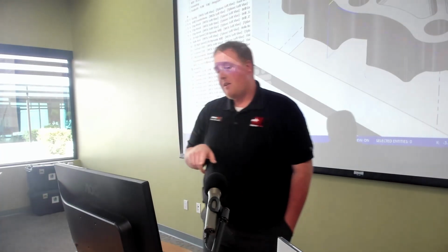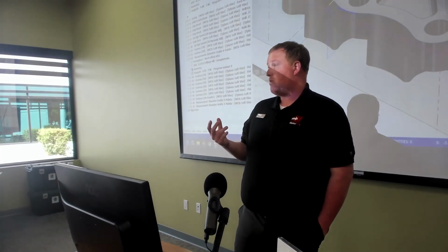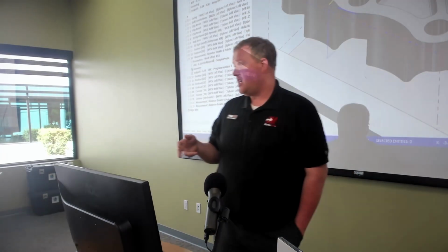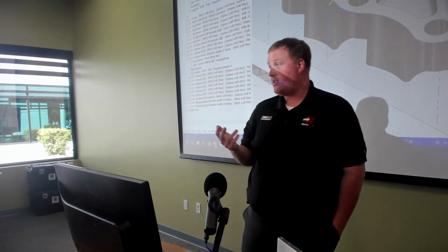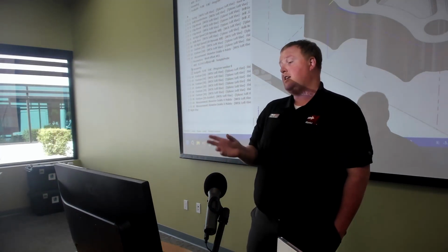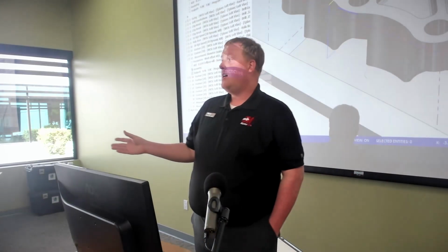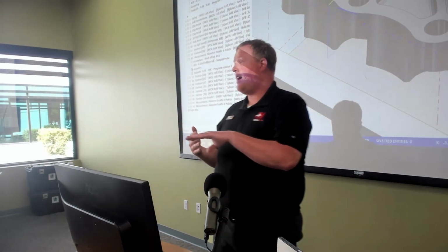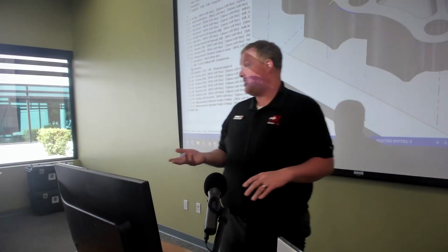As long as you have the option enabled, the Renishaw macros do allow for a T number, which is the tool number that needs to be updated. You could also pair that with an F, which is their feedback percentage. If it's just the T, it's going to comp the tool by 100% of the deviation that it found. The F in conjunction with that says, maybe I only want to update 60% of the deviation found.